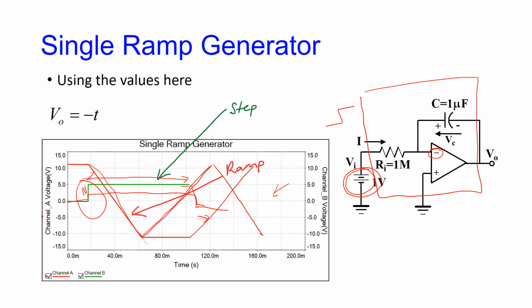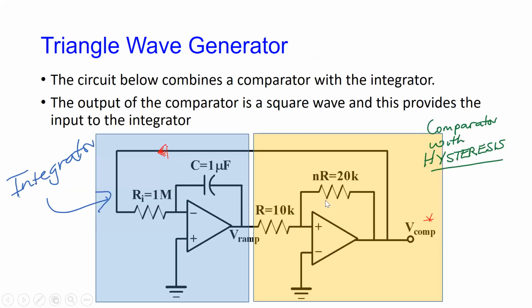So to do that, what we did is add this extra little bit here. This whole comparator is giving me that square wave going positive and negative at exactly the right point. It is timed in such a way that when this goes up, it will switch down and switch up exactly at the correct points when this is changing. Yeah, that makes sense.